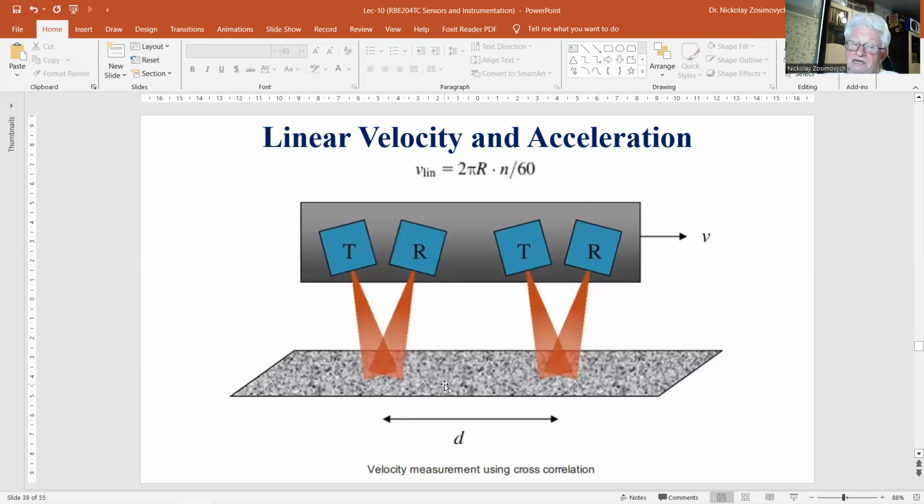The S to N ratio is adversely affected by vibrations or other movements like roll and pitch of the vehicle, misalignment of the optics, and surface characteristics. Moreover, a high speed requires a high sample rate to obtain a reliable correlation function, whereas at low speed, the delay time is long, which necessitates longer processing time to avoid large measurement errors.